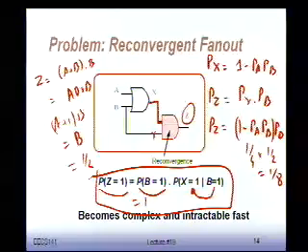So the only way to really do this is to take your data patterns with the right inputs and do a high-level simulation. You don't have to simulate this at transistor level. If I can simulate this at logic level, I apply my patterns and just simulate the ones and the zeros through the thing. I don't care about timing, I don't care about size of transistors or what logic style you use.